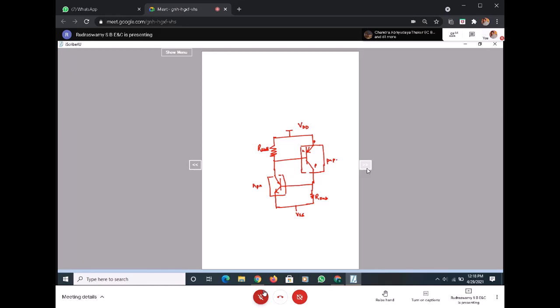Just now we saw if this particular voltage, if I call this node A and I call this node B. Node A is nothing but what? The base to emitter voltage. If this is something like 0.7, here the collector current will be simply beta times of IB. And now this is the NPN transistor. Now I'm going with the PNP transistor, right?